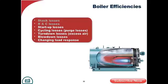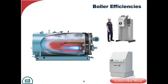So let's look at those. Well, we've already addressed the stack losses and the R&C losses, so we'll move right into the startup losses. Startup losses really assumes that a boiler is offline and it's cold, so it's at ambient temperature. Now here I've got a fire tube boiler, which has got a lot of mass, right? It's 5 square feet per boiler horsepower, against a vertical boiler right here that has far less mass, let's say. Maybe it's only 2 or 2.5 square feet per boiler horsepower.